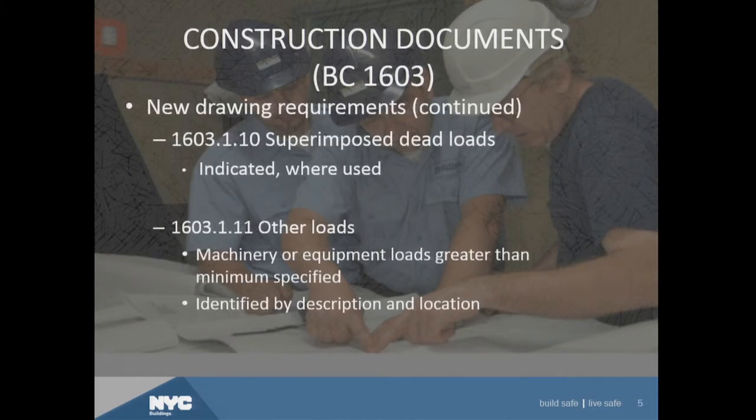A little more on some new structural design provisions that were added by our committee, and these are primarily committee enhancements. Superimposed dead loads. When a structural design incorporates the use of superimposed dead loads as part of the design, then those superimposed dead loads have to be indicated on the construction documents as part of the 2014 Code. There are no superimposed dead loads specifically called out in the code, so that's not something that's being done. But if the superimposed dead loads are used as part of the design, then they need to be indicated on